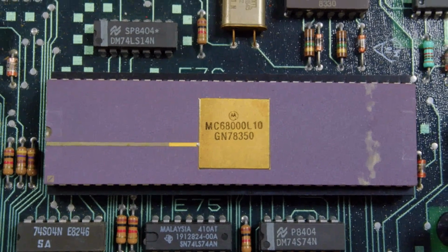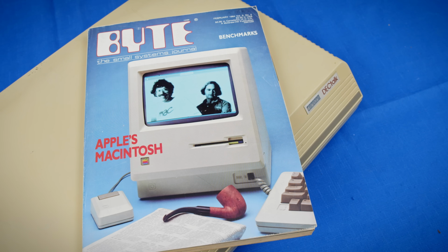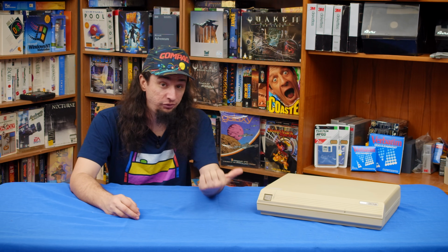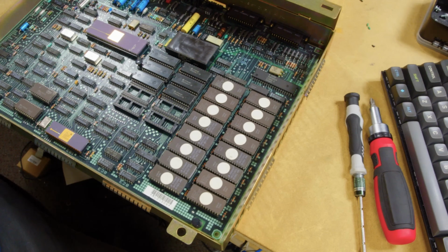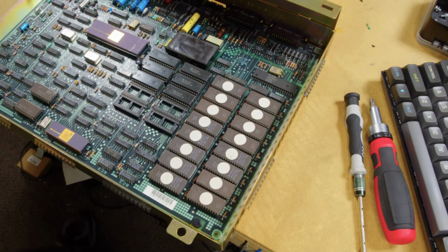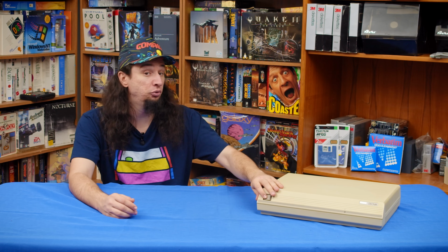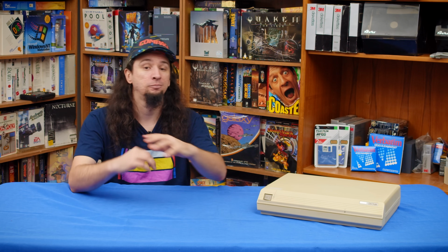While we're in here, we can see the Motorola 68000 that works as the brains here. This was the same processor you would get in the Macintosh that released in the same year as this did, so this was a respectably powerful device. Inside, we can also see static RAM and the 16 ROMs that make up its firmware and phonetic dictionary. The example I have here came with the earlier 1.8 firmware revision, something the DECtalk itself tells you every time you turn it on.